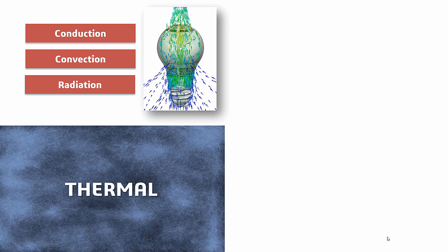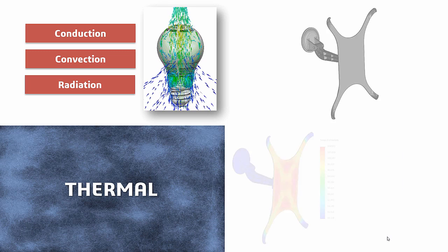Now we are actually able to simulate all three forms of heat transfer, except in convection. Although a fluid dynamics tool is better because it's able to simulate both the solid and the fluid media, we are actually able to fool the software or simulate the presence of a liquid by applying convection coefficients.